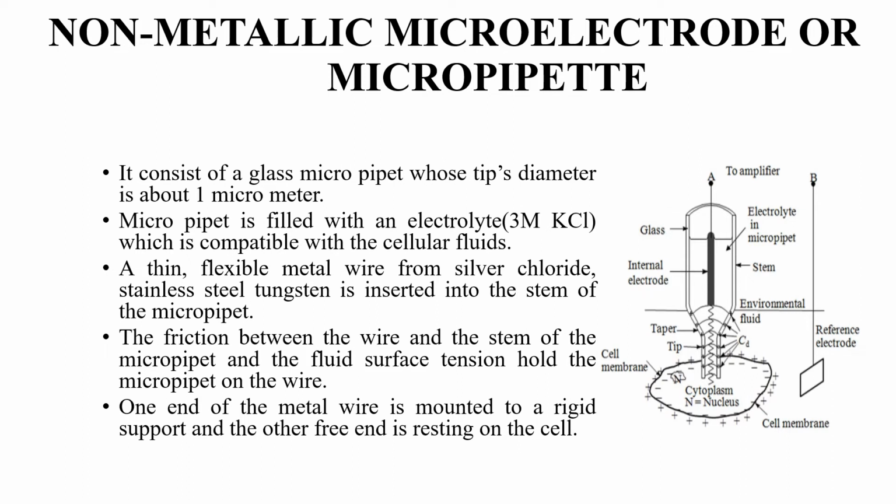The active tip is the metallic area; metals such as silver solder alloy and platinum, and silver alloys are used. The section of fine bore glass capillary is heated with a burner to the softening point. It is then rapidly stretched to produce a constriction.